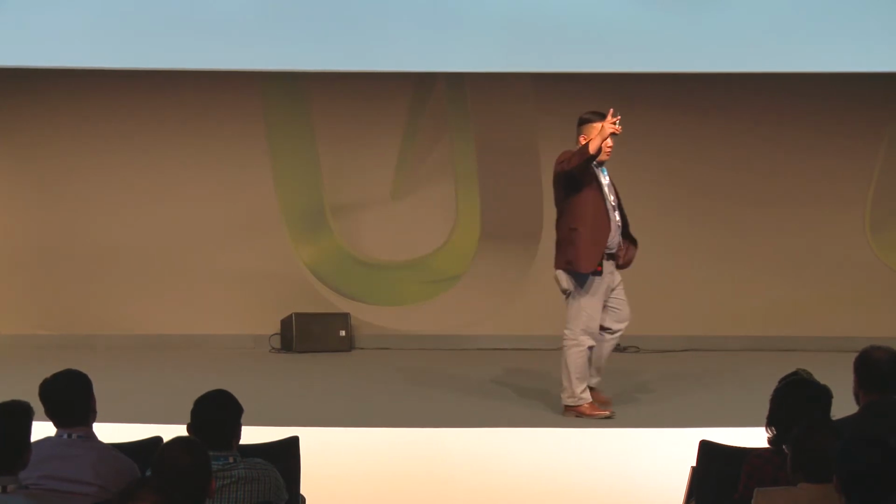Do you know that there are 2 COBie templates out there? For those who are BIM managers, BIM directors here working on a project, do you know what is COBie? And do you know that there are 2 variations of the COBie template out there? There is a US COBie 2.4 template, and there is a UK COBie 2.4 template. The US uses the Omniclass classification system. The UK uses the Uniclass 2.0 classification system. So the difference between the two, there's actually not much difference, but the UK tends to have more requirements in terms of data fields. So that's why it is very important to indicate which type of COBie template you're going to use in order to set out correct expectations.